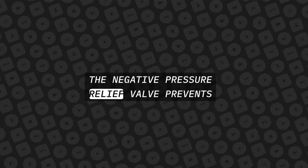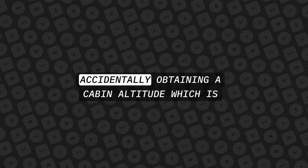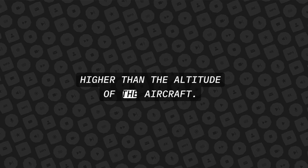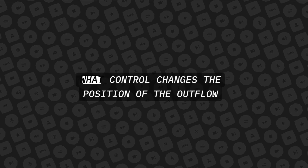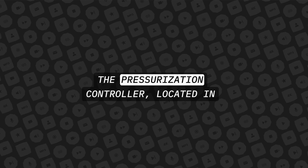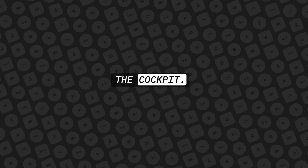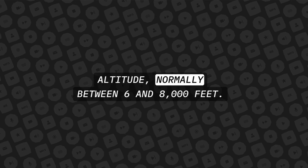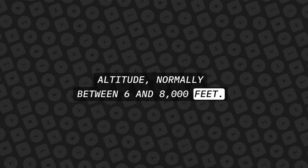The negative pressure relief valve prevents accidentally obtaining a cabin altitude which is higher than the altitude of the aircraft. What control changes the position of the outflow valve? The pressurization controller, located in the cockpit. It is used to set the cabin air pressure to a desired altitude, normally between 6 and 8,000 feet.